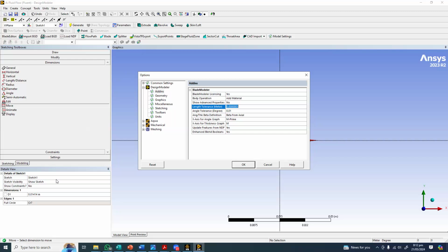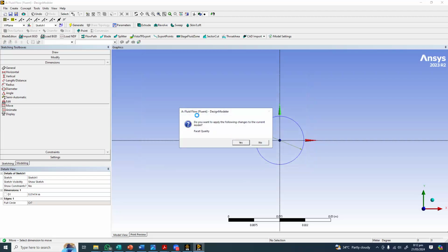Okay, because default tolerance for millimeters will be way below what we are going to actually model there. So my suggestion is that we should go for millimeters, but for this case we already have a lot of tolerances set there. But if you reset, you see this is 1, 2, 3, 4, 5. So here the number is 1, 2, 3, 4, 5. Okay, this number will be okay. But if there's some number that has 6 places, then we have trouble. So I would suggest that we should change the units to millimeters.